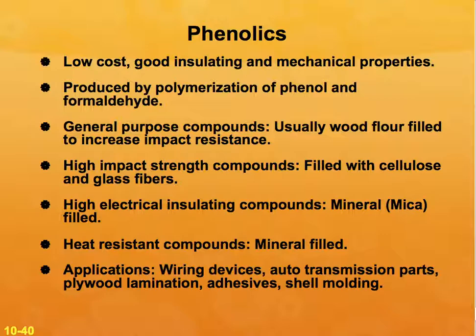If you want really high impact strength, then you add cellulose and glass fibers to phenolic resins. And if you want highly insulating type of compounds, then you can fill them with mica.